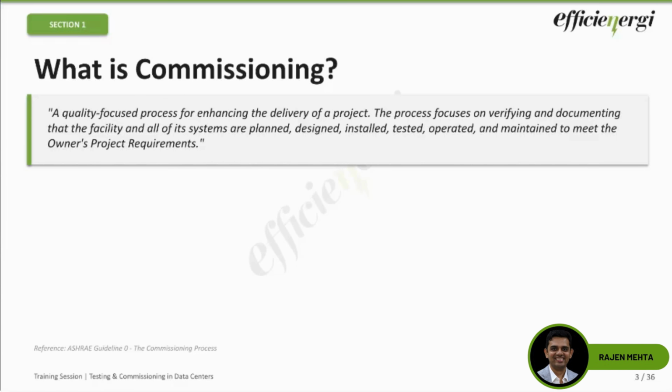Now, commissioning is what? Number one, documentation and validation of design intent. Did we build what was designed? Does it work as intended? That's most important. Second, systematic verification at every project stage, not just at the end, from design through operation, at any different levels that is necessary.